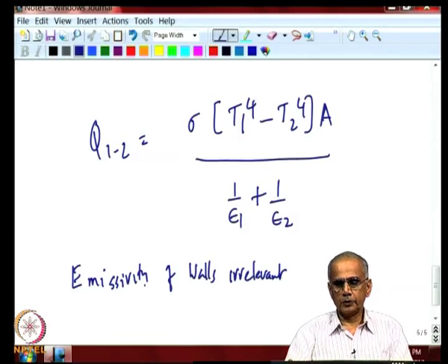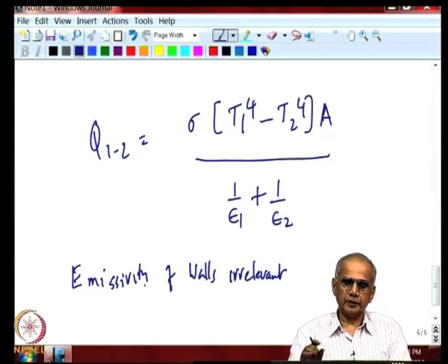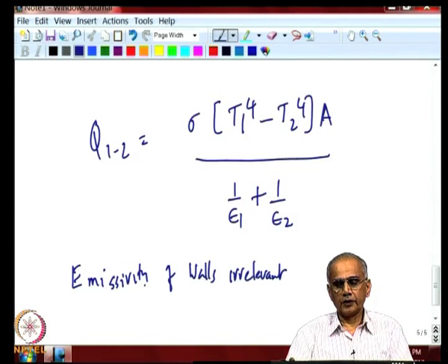So, similar to what we saw in the case of the furnace, the refractory walls are large, the emissivity of the walls is not relevant, same thing here. So, the room is very large, it does not matter what emissivity or reflectivity it has, ultimately it behaves effectively like a black body.